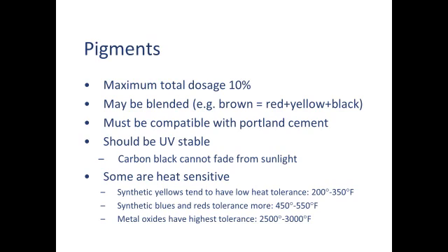Whenever you're using pigments, whether it's liquid or powder, never exceed a maximum dosage of 10% with Portland cement-based concrete, because the more pigment you add, the more you're weakening your cement paste. Liquids, they're basically powdered pigments in a liquid suspension. So there's a liquid with a suspending agent, and they add a powder to it, blend it together. Just like latex paint, you go to the hardware store, you buy a can of paint, you have to stir it. Liquid pigments probably have to be stirred. There's suspension. I treat them the same way.